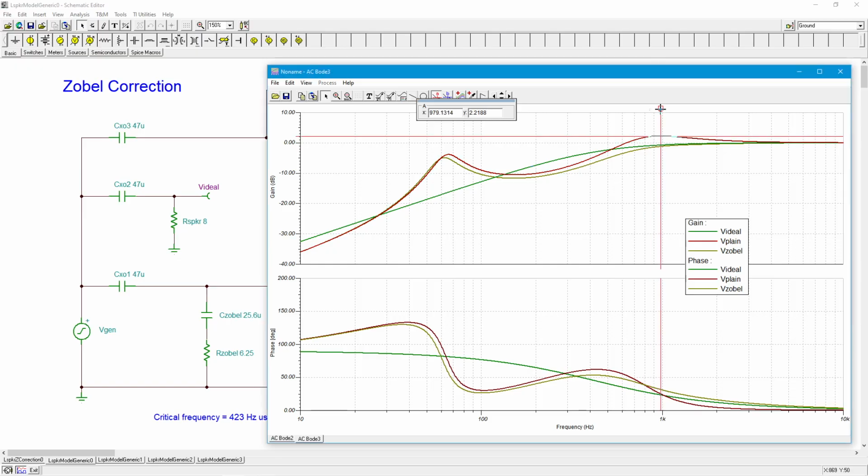That's coming up. All right, it's about 2.2, maybe 2.25 dB. Right, so that's not something we would want to see. So I've got this rise up here, about an octave above the crossover. And then we've got this similar rise in the bass end, okay? Quick look at the phase response. We can say this is kind of funky compared to the idealized phase response.